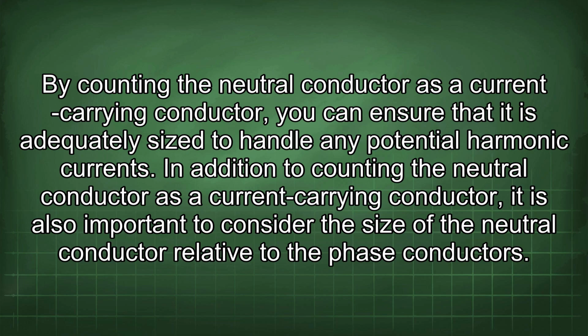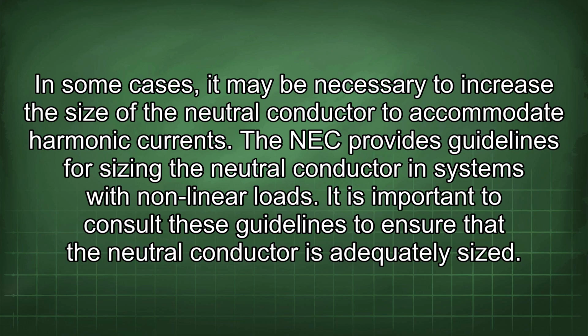In addition to counting the neutral conductor as a current-carrying conductor, it is also important to consider the size of the neutral conductor relative to the phase conductors. In some cases, it may be necessary to increase the size of the neutral conductor to accommodate harmonic currents. The NEC provides guidelines for sizing the neutral conductor in systems with nonlinear loads. It is important to consult these guidelines to ensure that the neutral conductor is adequately sized.